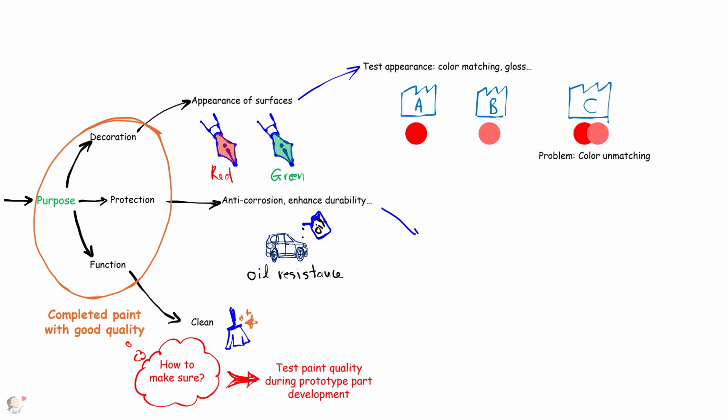Next, the paint's ability to withstand external forces is tested, such as with a pencil hardness test. Let's assume this is the substrate layer with the paint layer on top. Pencils of different HB hardness levels are used to rub against the paint to see how many HB levels it can withstand. And there are many other tests depending on the product's quality requirements.